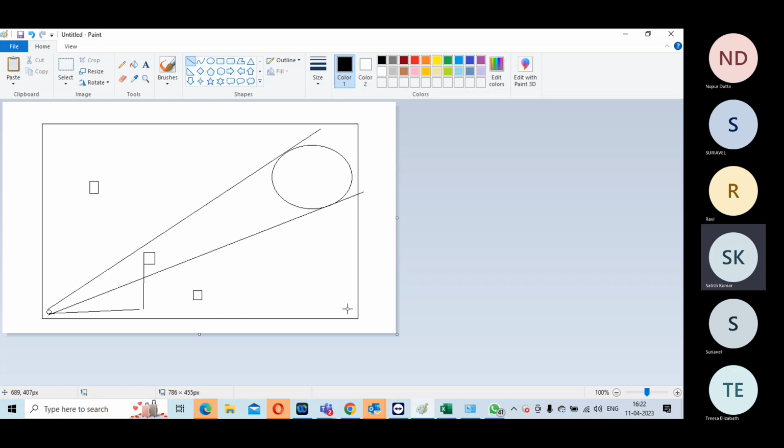Sir, what about target skew, sir? See, target skew, I said, should not be more than 5% of your clock period. 5 to 10% should be your max skew target, because more than that means you are shrinking the timing path, it is causing a lot of problems for you. 5 to 10%, because 5% will anyway come from jitter, so they may allow 5%. You can say we should not exceed more than 10% of the clock.